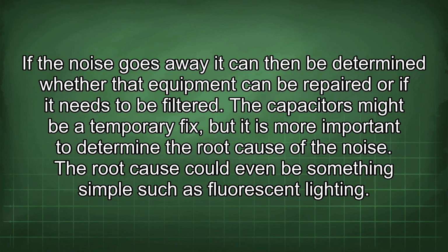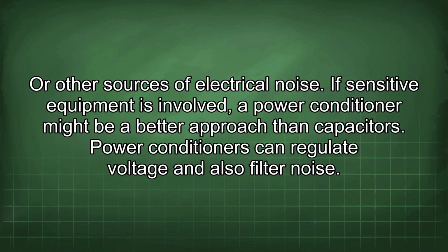to be filtered. The capacitors might be a temporary fix, but it is more important to determine the root cause of the noise. The root cause could even be something simple such as fluorescent lighting, or other sources of electrical noise. If sensitive equipment is involved, a power conditioner might be a better approach than capacitors. Power conditioners can regulate voltage and also filter noise.